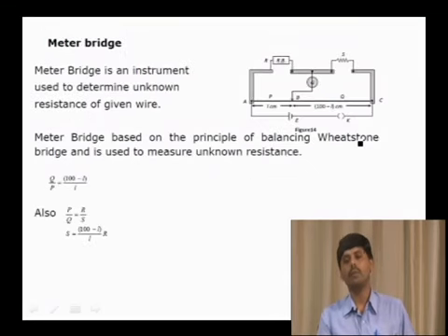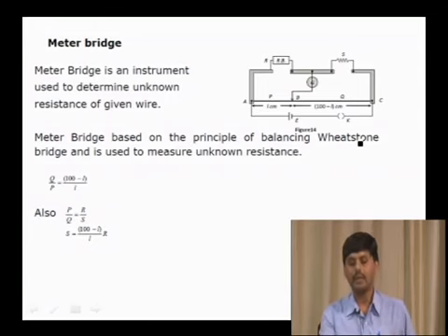Yes. Next we will move on to the applications of the Wheatstone's network. The first application is the meter bridge. I think the students are very familiar with it, as in the laboratory we use the meter bridge. This meter bridge is an instrument used to find the resistance of an unknown wire. It works on the principle of the balanced Wheatstone network.